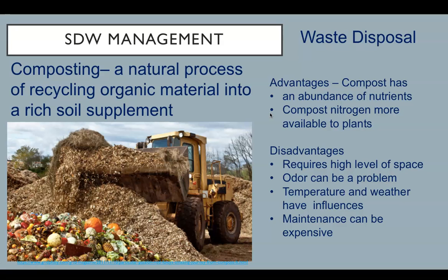The main disadvantages of compost are the following. It does require a large amount of space, right? If you have to aerate these piles and turn them over, you need space. Odor can be a problem. And ambient temperature and weather can have an influence on the composting. In-vessel containers are expensive and have limited flexibility to handle large quantities.